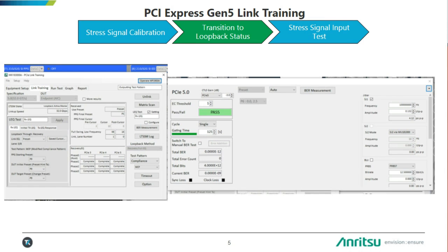Another important step is, once the DUT gets looped back and you see no errors, make sure to insert errors, and that your DUT loops back that error also, and the error detector detects that inserted error. So this function here, you can use to insert errors. Just make a sanity check of the loopback. Some DUTs just spontaneously generate the pattern. In that case, you cannot make any test.